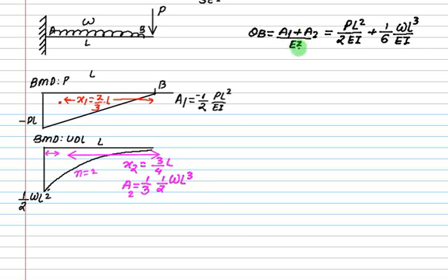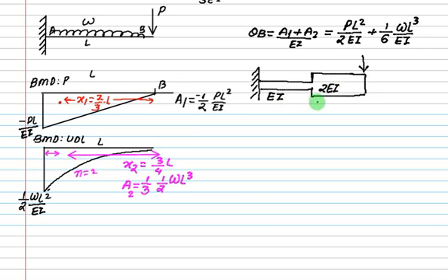When you are writing EI, you actually have to construct one more figure, and that figure will be like this, with this divided by EI and this divided by EI. Now in my problem I have stated that my EI is uniform, so this will not change. But if I say that my beam is like this, is it still a cantilever? Does this beam have the same EI or is EI different? EI is different. So this one is 2EI. Now this is the point load.